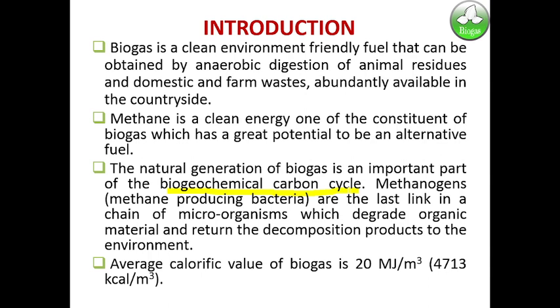Because you have to replace this oil, a special kind of engine should be designed. Diesel engines have been modified to run 100% on biogas. Petrol and CNG engines can also be modified easily to use biogas. Biogas has a high quantity of methane, so instead of CNG, you can directly feed the biogas produced from the biogas plant to run your vehicles.